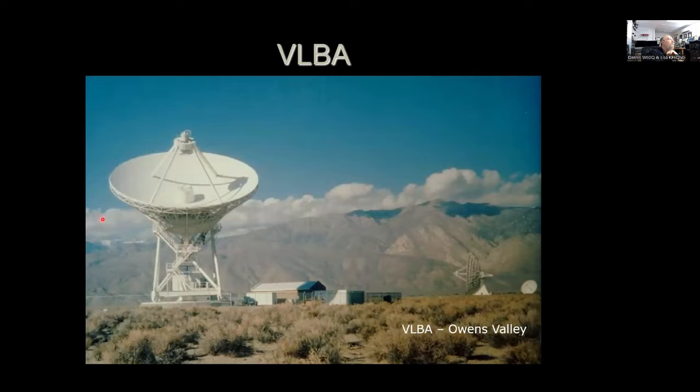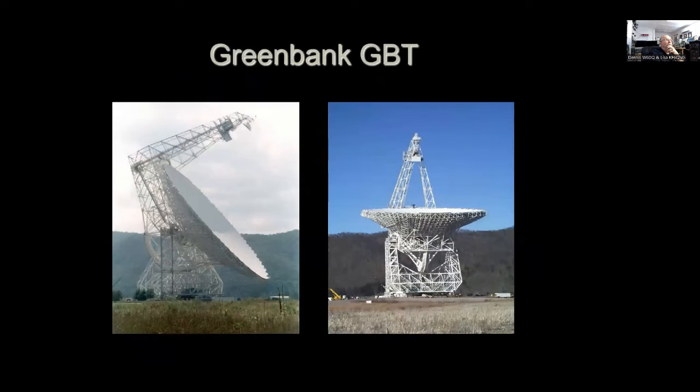Interesting. If you think about it, this is an interesting aspect of this. If I look at something like this, it's quiet. This antenna is a single dish antenna. This is the feed. This is a Cassegrain feed. This is where the feed horns are down here. This is a subreflector, and there's the feed horns. One of the things you note about this is you've got this structure, and the structure causes interference with the incoming waves. So it does degrade the signal because of all this structure. If we look at GBT, this has a rather unique design for a radio telescope. Take a look. If you've got DirecTV or Dish, any kind of satellite television, DBS system, it's called an offset fed.